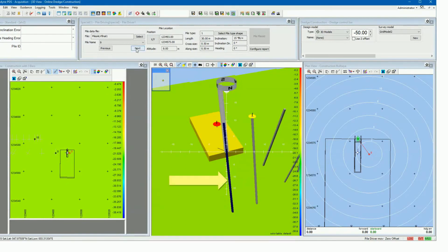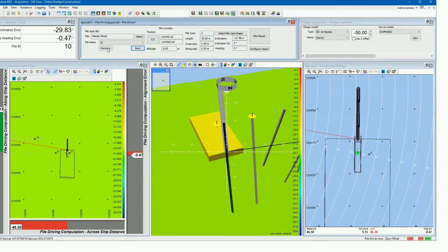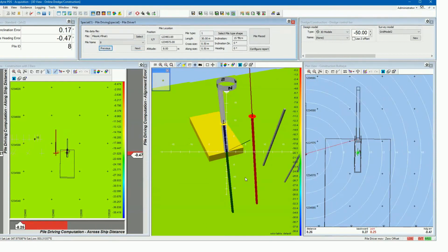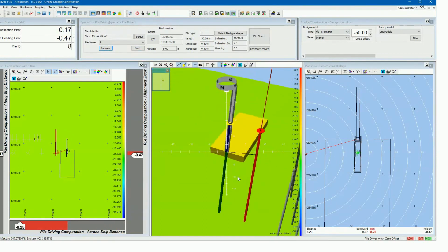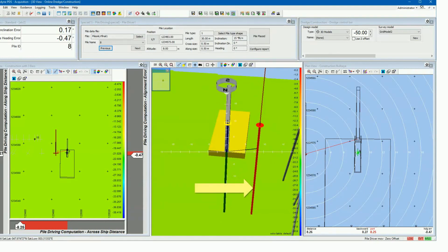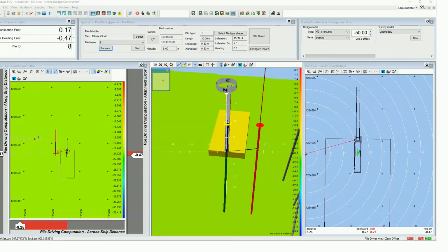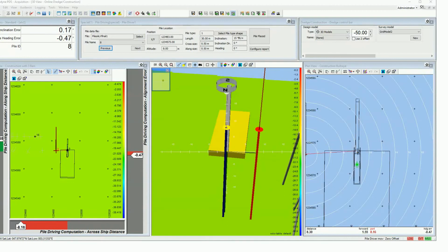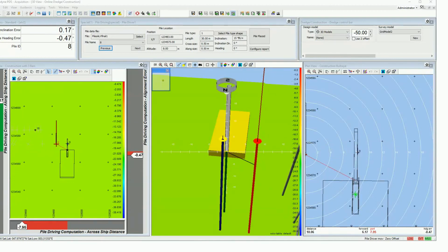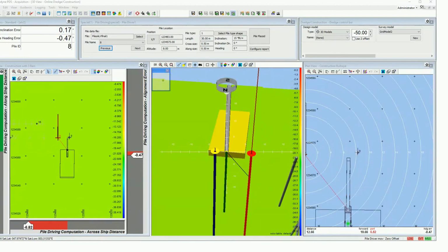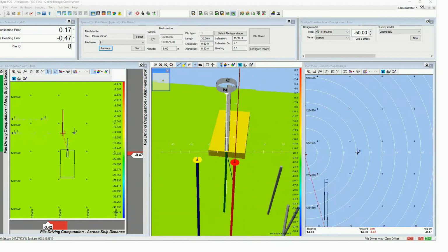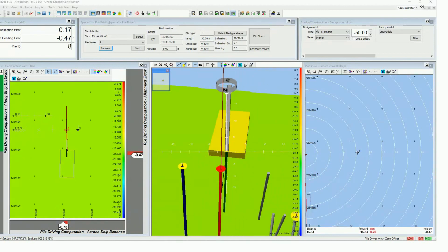The views are updated such that the pile set point is replaced by the placed pile position. We select the next pile of the pile data file. And start the process again by maneuvering the pile driving rig to this location. And in position we drive our pile again.